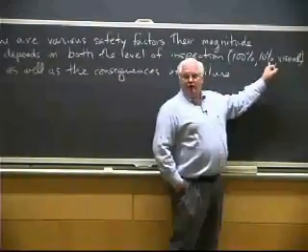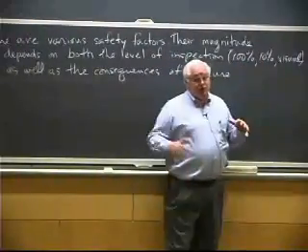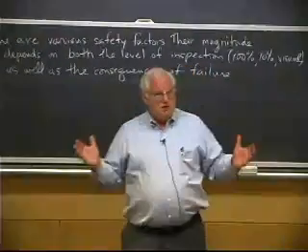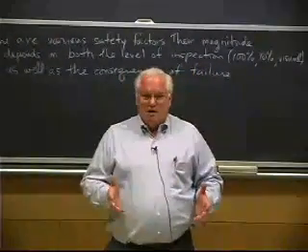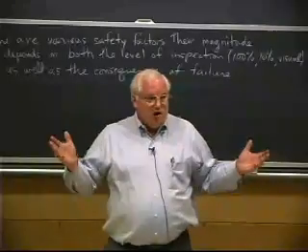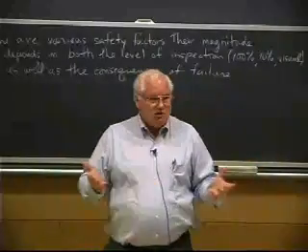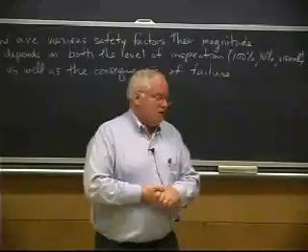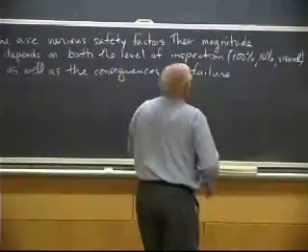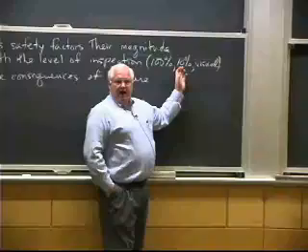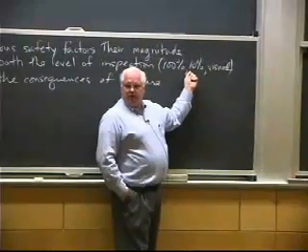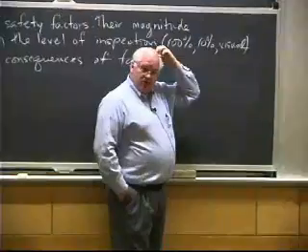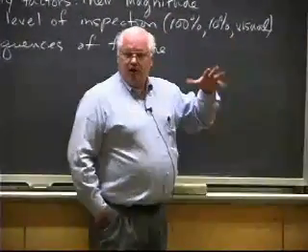If I'm only going to do a random check, which means I'm just trying to make sure the quality process is in control, there's a fair chance that in those other 90% of the uninspected parts I've got something larger than that eighth of an inch flaw, or whatever my limitation is on my defect size. So I need a bigger safety factor to allow for the lower level of inspection. So safety factor goes down as the level of inspection goes up. Of course, costs go up, so there's a trade-off here.